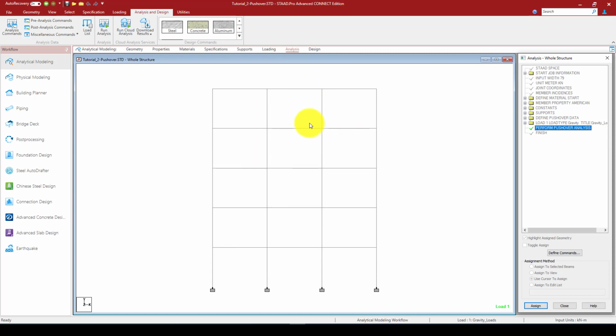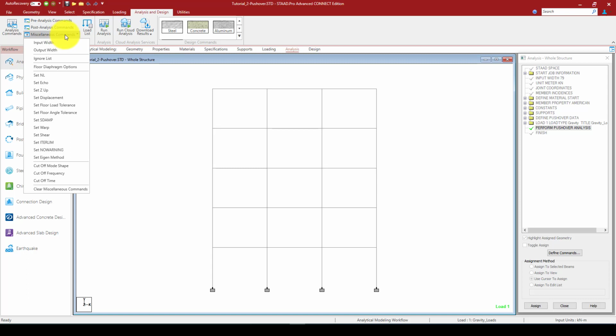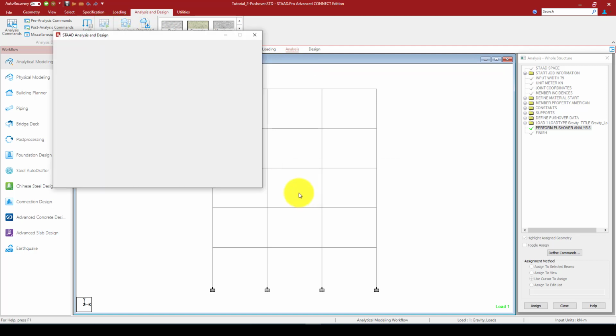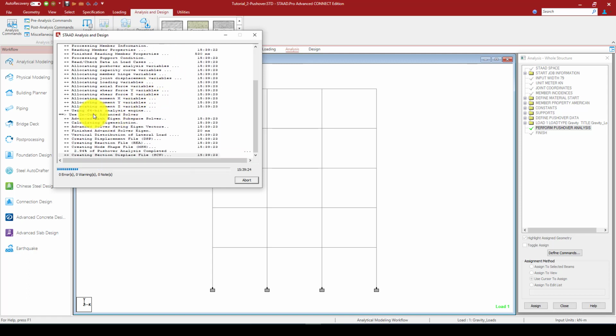I'm going to add this one in case you want to see some mode shape, some frequency as well. You can come to the modal command, and you have to give some kind of mode shape. We do not require it in this one because we have defined the direction and also the node. Now we are ready to run the analysis. I'm going to save the model, and it starts to run. It takes a while to finish.